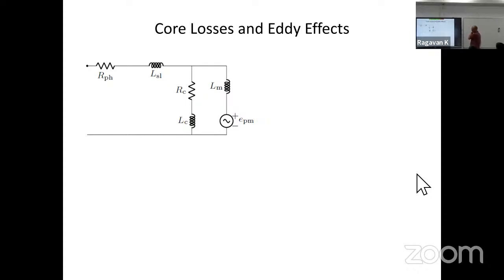Yeah, so there is some loss here, right? In the circuit, we understand that some current is going here, V squared by R. As E_B increases, there are more losses here. So whatever you measure at the terminal, you can write the equation and check that. You can write a Thevenin equivalent voltage at the terminals and see that it decreases.